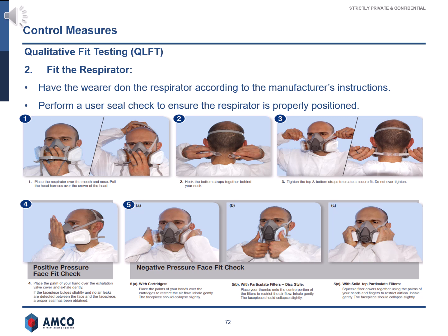Positive pressure face fit check. Place the palm of your hand over the exhalation valve cover and exhale gently. If air escapes between your face and the face seal, readjust the head harness straps.